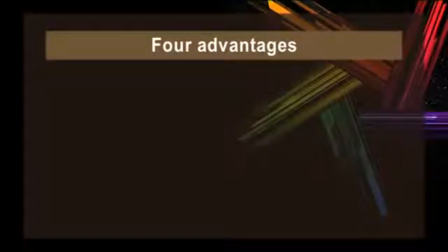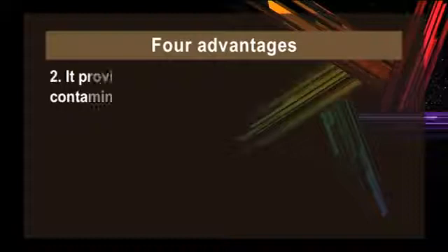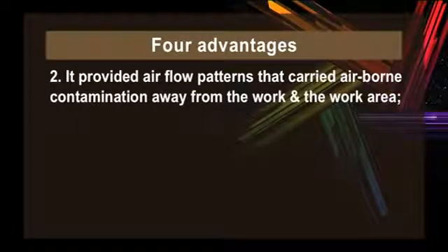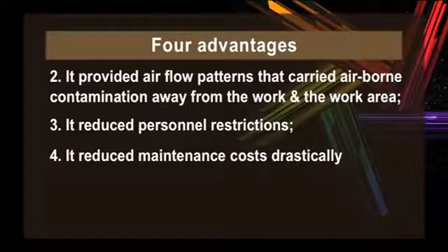Four advantages of this type of airflow control were obvious. One, it provided the clean room with a self clean down capability to remove contamination brought into and also generated within the room. Two, it provided airflow patterns that carried airborne contamination away from the work and the work area. Three, it reduced personal restrictions, and at last, it reduced maintenance costs drastically.